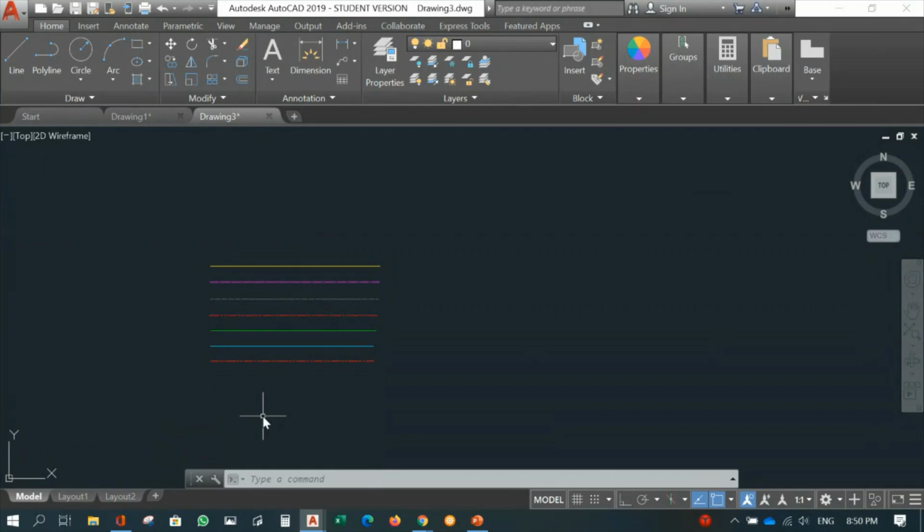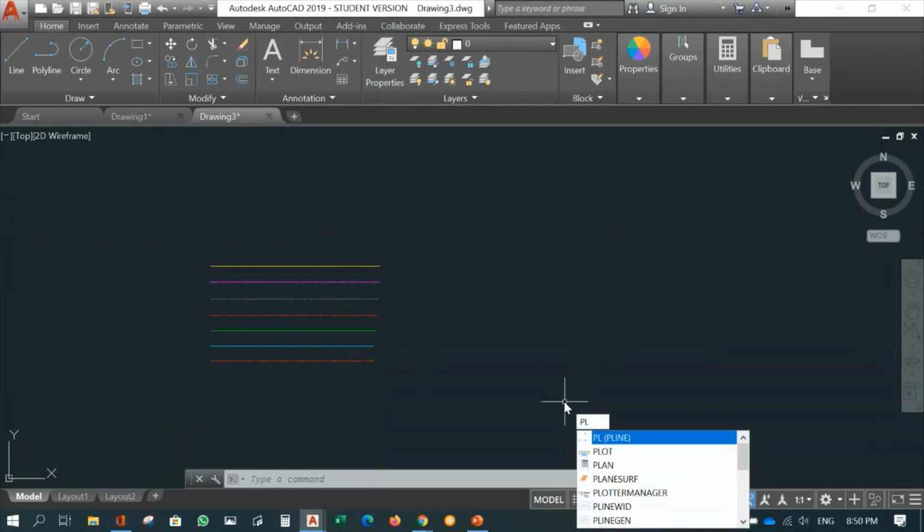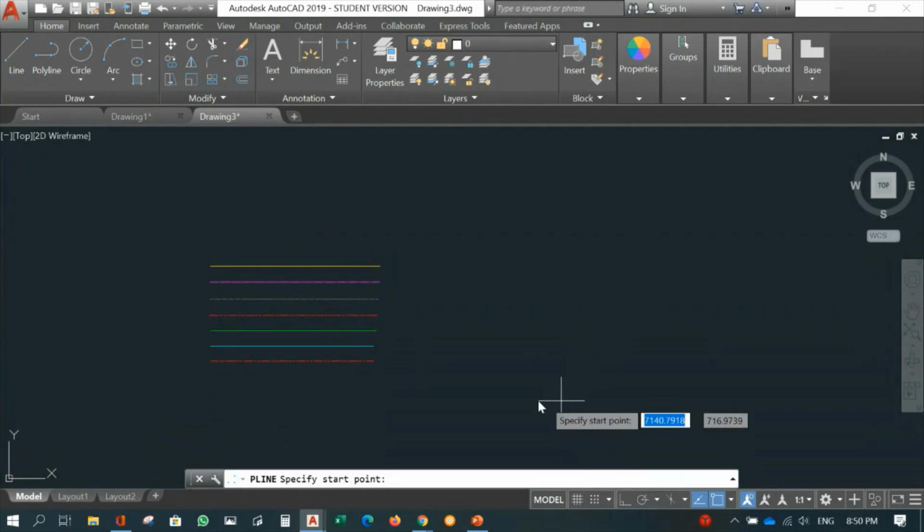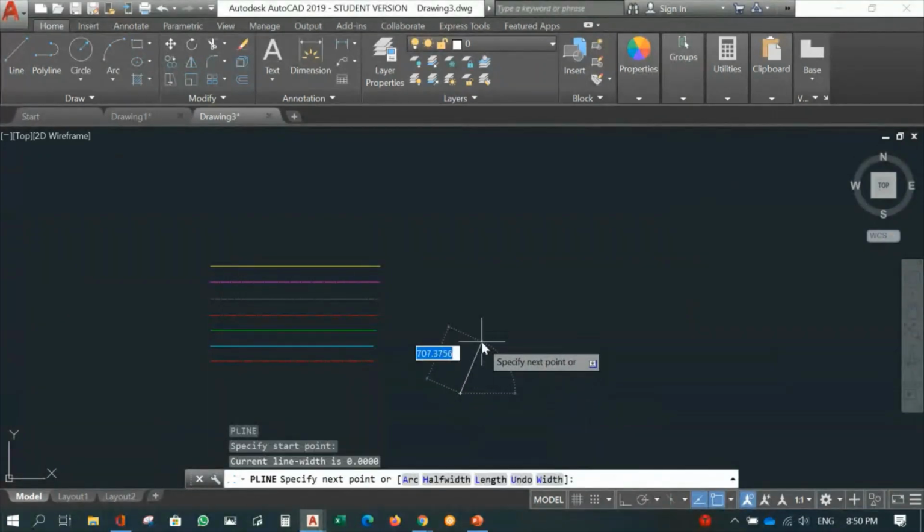But that does not happen in AutoCAD. In AutoCAD, everything must be in one-to-one scale, right? What we're going to change next is only during the printing. All right. For example, let's say we have an A4 paper, the size of 210 times 297. We did this before.